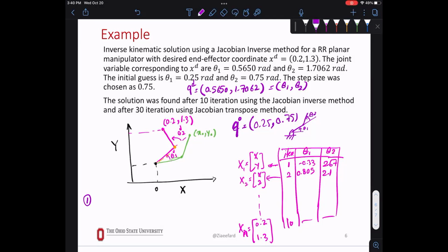Now this x and y is your new current position, and you had your theta 1, theta 2. So you're changing your theta 1, theta 2 from time 0. You add the step, let's say add half a degree each time, and that's your new theta 1, theta 2. You plug back into the forward kinematics, find your new x and y, and then compare. This is the convergence. You're comparing for convergence. You go until you're happy.